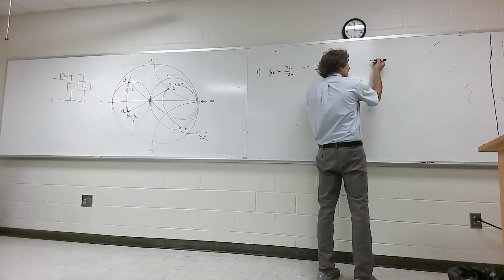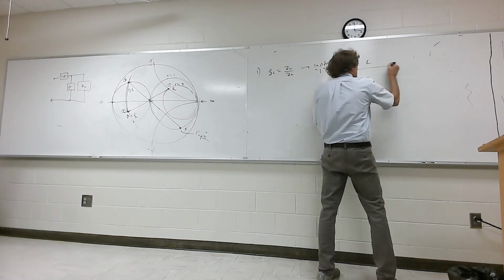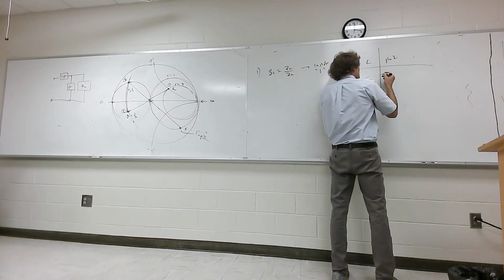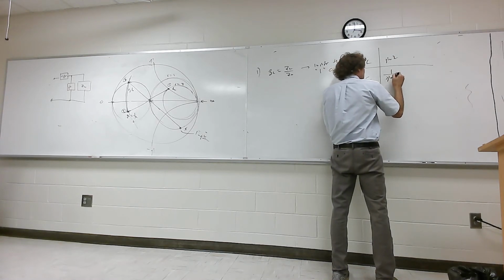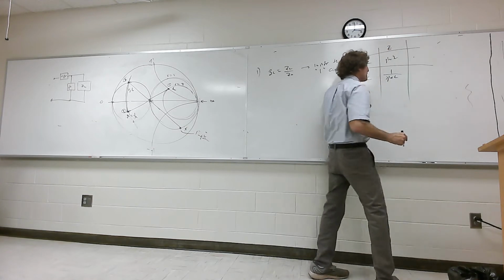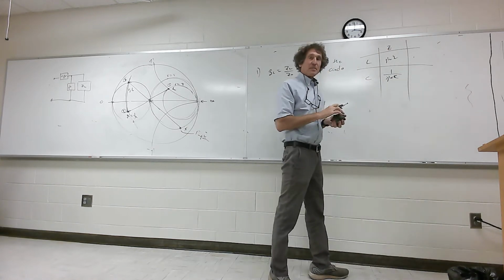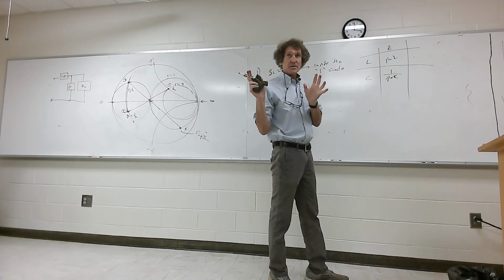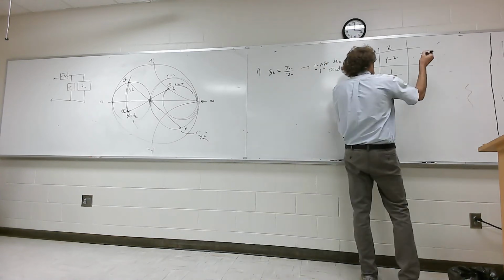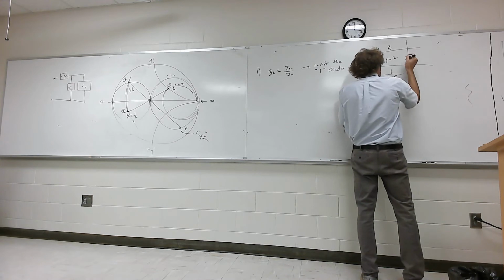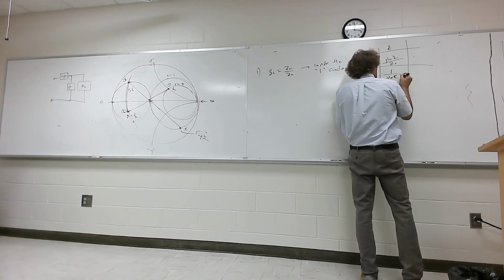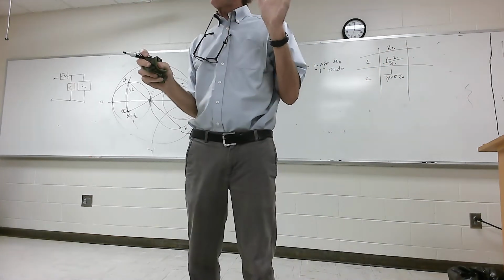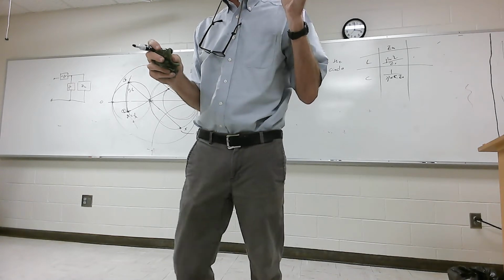If you have an inductor or a capacitor, the inductive reactance is J omega L. The capacitive reactance is 1 over J omega C. This would be Z for these elements. Y'all follow me? Now, if you normalize that, you divide by Z naught. Y'all hear me on this? You gotta normalize this stuff. So if you normalize this, then you would be dividing by Z naught, and I'll put that right here. Now these are normalized impedances. Y'all follow? Y'all get me on this one? Normalization means just dividing by the characteristic impedance.